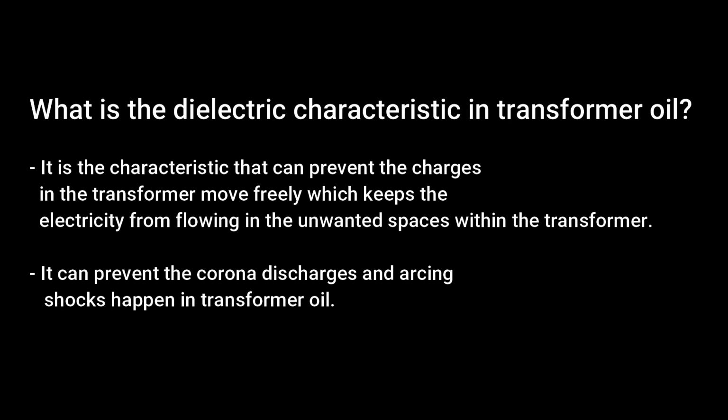What is the dielectric characteristic in transformer oil? It is the characteristic that can prevent the charges in the transformer from moving freely, which keeps the electricity from flowing in unwanted spaces within the transformer. It also can prevent corona discharges and arcing shocks from happening in transformer oil.